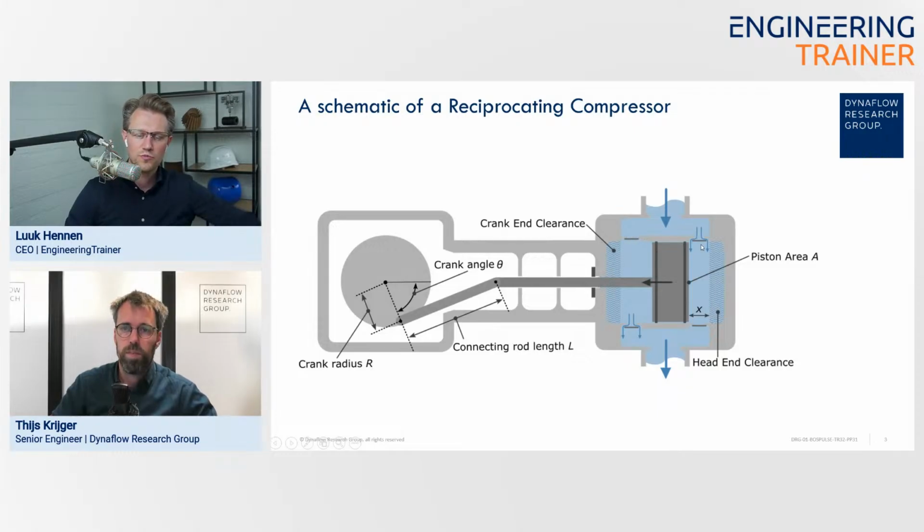So in either of those movements, the piston moving to the right or the left, it pushes out the gas into the pipeline one way or another. So this is possible. This is what we call a double acting compressor. It moves in both directions, to the right and to the left, and it'll produce flow.